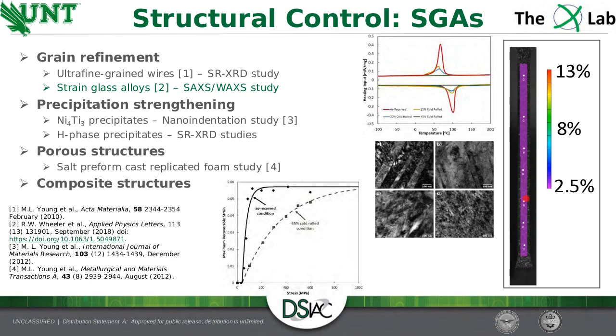And again, I mentioned it does a Luders-like band loading. This has a video, but the video is not working. What I would tell you is you see these propagate across the surface in a helical pattern. It usually starts at both ends, and they run and meet together. In a normal as-received material, you'll get a hot spot where you have a defect or a non-metallic inclusion, and you'd get early fracture there.